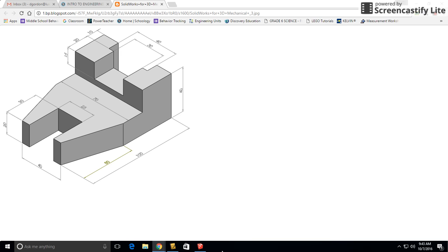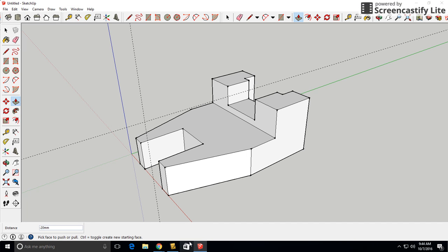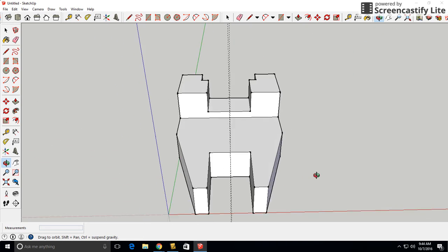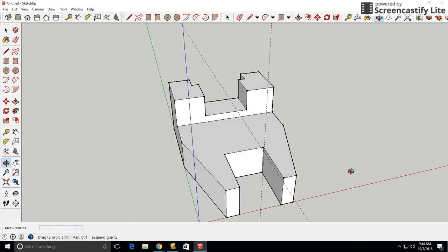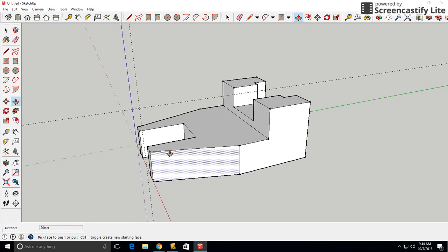This is part 4 of the tutorial for drawing 5. In this tutorial, we're going to add dimensions. Now, dimensions, to this point, we haven't used at all. We've only read them off of the prints, but I want to show you how you can add dimensions in using SketchUp. Now, the dimensions are in the large tool set, and this is the dimension tool.